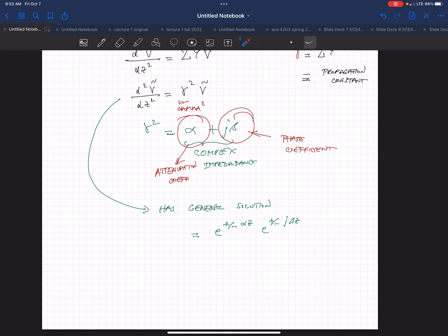But now when we added these resistances and ended up with this lossy transmission line, we added this exponential that no longer has the j in it. As I increase z, this is going to be a real exponential, e to the minus alpha z. That means my amplitude is going to start going down as I go in the forward direction of transmission. So by adding these resistances, we get an actual loss in the amplitude of the waveform as you go through z.